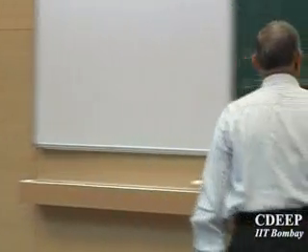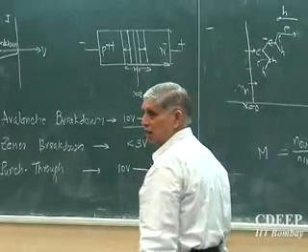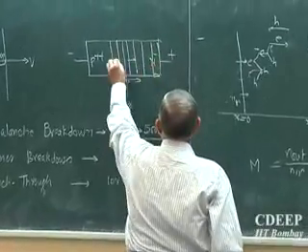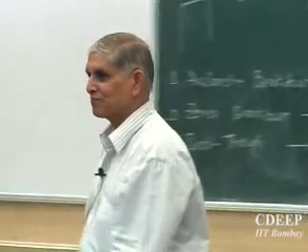Since you are depleting, it may occur at a certain voltage that the whole of this N region gets depleted. If your diode lengths are, say, 10 micron, 100 micron, 50 micron, at a given bias of VR, before avalanche occurs for that device, the widths may be such that at that reverse bias, the whole N region gets depleted.